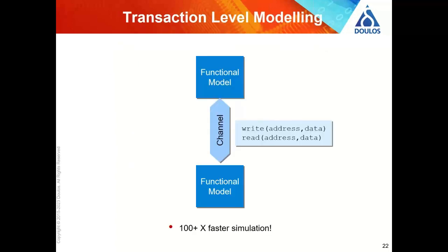In transaction level modeling, it works best with things like bus activity, because we can replace, say, a complete operation on a bus with a function call. So rather than having to represent separate events for each bit of each wire on that bus, on every clock cycle, we can have a single event corresponding to a read or write function. Okay, we're losing low-level details, but maybe that doesn't always matter. SystemC does exactly that with transaction level modeling. UVM has borrowed those ideas into the transaction interfaces that are used between UVM components and the UVM environment.